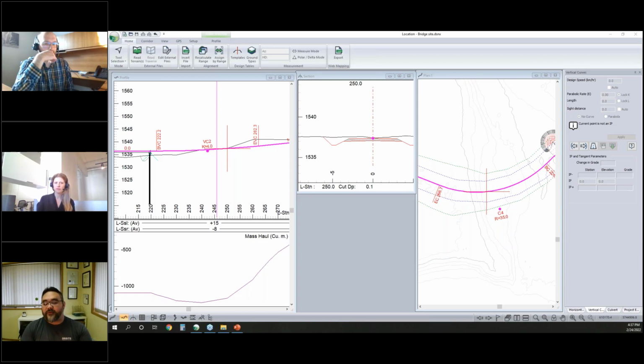Generally how that starts is just grab samples on the ground surface, and the geologists generally take care of that. You could chip them off and send them in for testing, and that gives you your first pass of whether you think you're going to have an issue. On the mining side, that's often followed up by a drilling program.